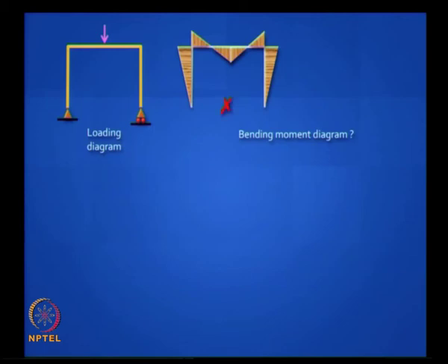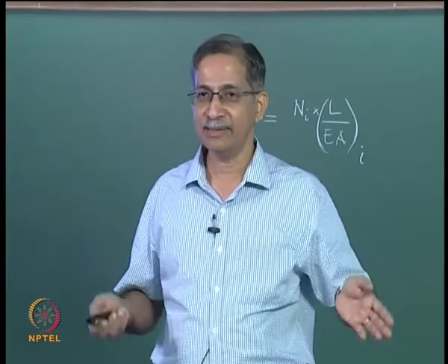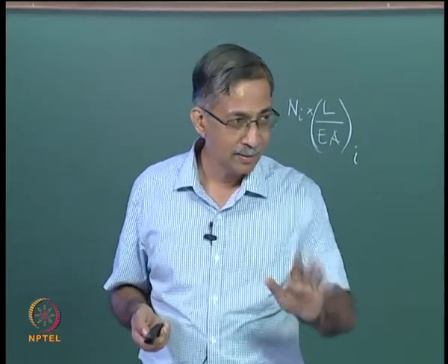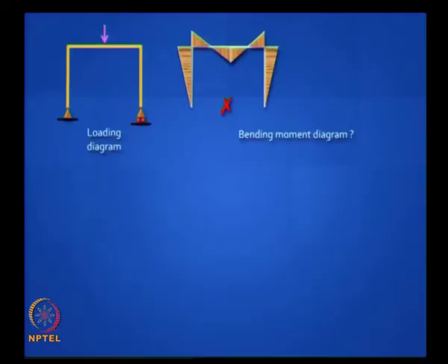So the vertical components, there is no bending moment. Yeah, so there cannot be bending moments in the vertical components, that is the columns. Why not? Sir, only axial loads are there. No. Why only axial load? Sir, because only vertical reactions are there and no horizontal. No horizontal reaction. You see, you can't have a horizontal reaction at the supports in a simply supported beam subject to only vertical loading. So if the horizontal reaction is not there, you can't get a bending moment in that vertical element. So this is wrong.